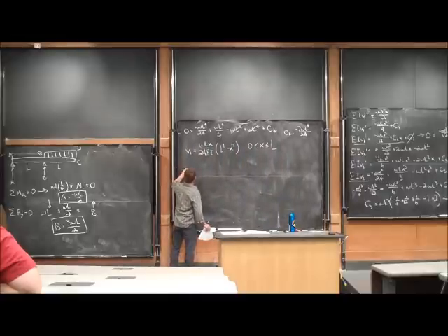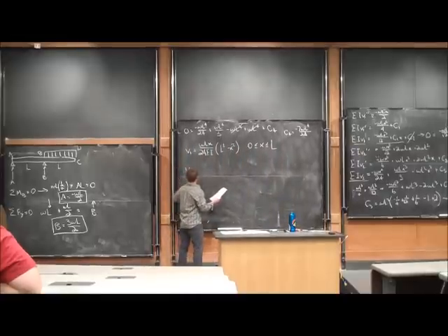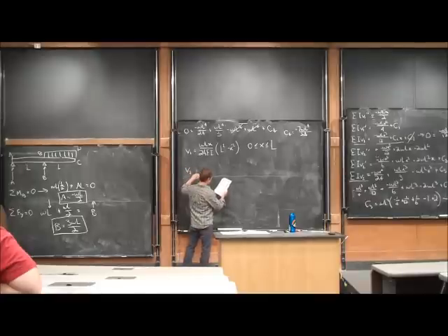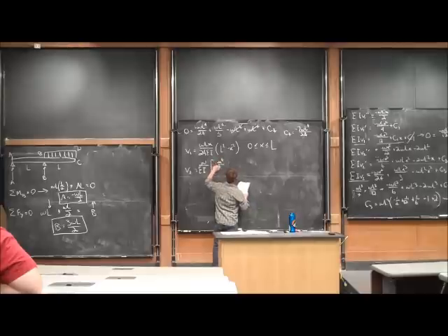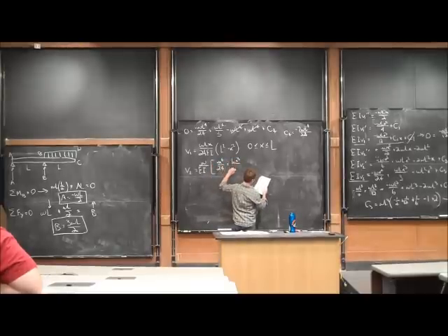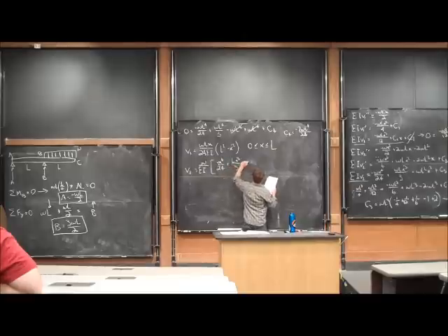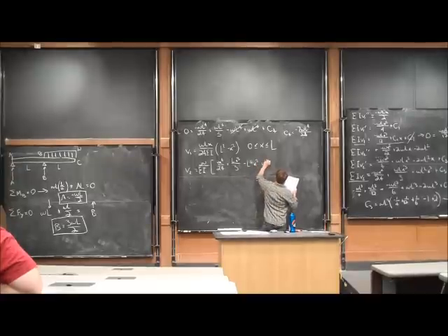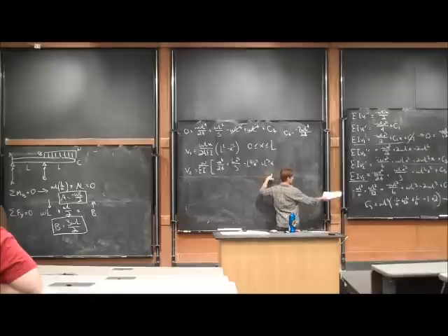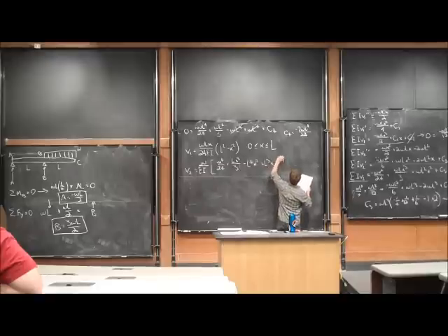And we saw we could find by plugging in what we got for our other 2 integration constants that V2 is going to be equal to W over EI times negative X to the 4th over 24 plus LX cubed over 3 minus L squared X squared plus L cubed X minus our last integration constant, minus 7L to the 4th over 24.